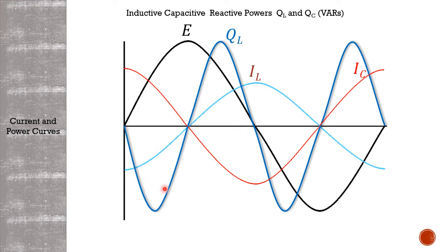You will notice that my inductive power now is twice the frequency of my voltage frequency. And my inductor is constantly playing this game of discharging and charging. So it's giving me energy back, and then it's storing energy. It's giving me energy back, and it's storing energy.